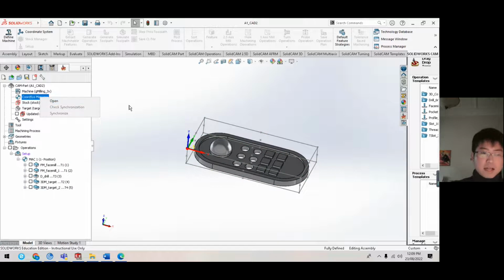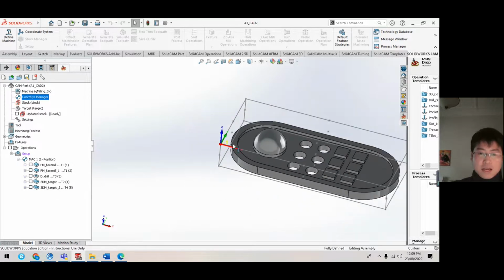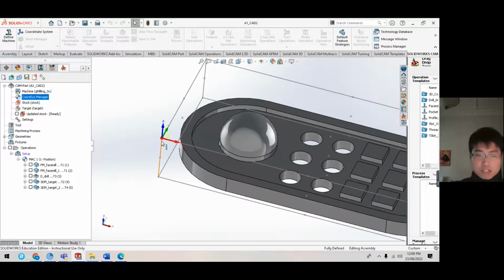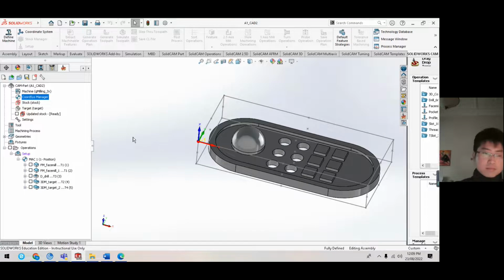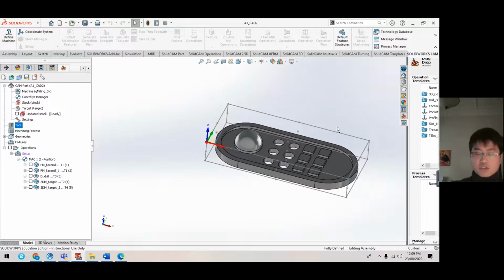Then after that, I choose my coordinate system at the left top bottom of this point as a datum point, from which we will start all the procedures in the later process. After we set up all the default settings of the CNC machine, we will use two rectangular blocks to hold and lock two sides, like my mouse area, for this stock object.